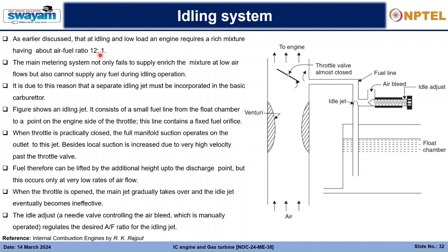Because the pressure differential between the engine cylinder and the exhaust valve is not high, dilution of the charge happens when the unburned gases are not completely removed from the cylinder. They mix with the fresh charge that is coming, and that reduces the efficiency if the fuel is not supplied at a higher amount. Since the fuel needs to be supplied at a higher amount, a rich fuel-air mixture is needed.